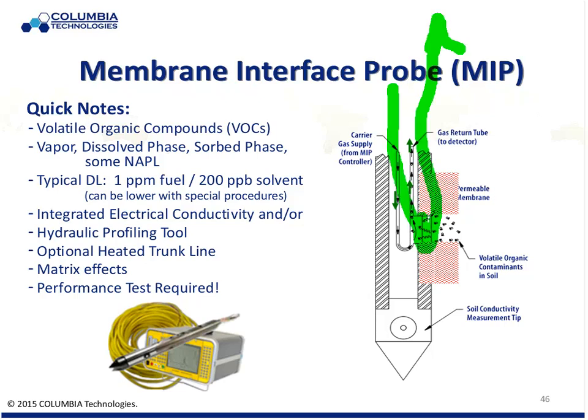So essentially what we've done is put a membrane extraction system with a purge and trap down here at the bottom of the hole. So we heat the subsurface, sorry about that. Heat the subsurface to 120 degrees. Typically, we'll do that for 30 to 45 seconds, depending on the type of compound. You want to do that consistently.